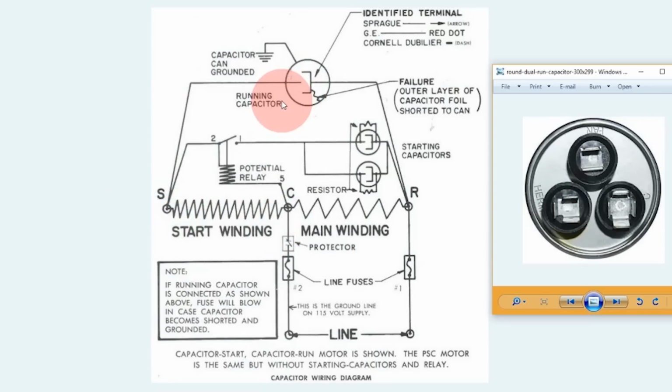So the amperage of your start winding is completely dictated by the voltage and by the capacitance. Now, some people will point out, well, your motor does add inductive reactance. When you measure between these two points, between start and common, you see a much higher voltage than the applied line voltage. And that's because of the back EMF that occurs within the start winding.